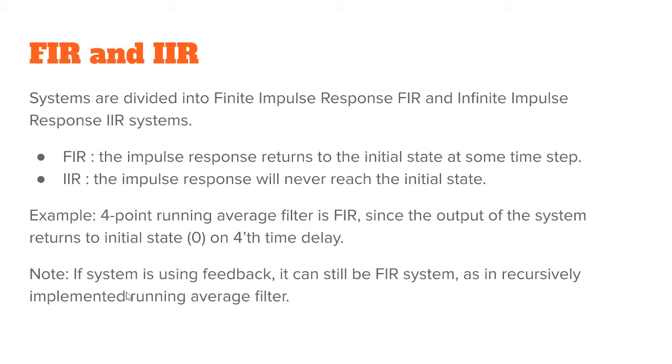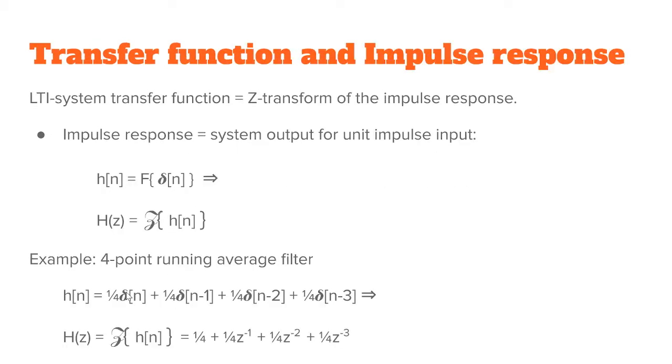That's the feedback when we take part of the output and put it back to the input, same way as you would do on the feedback on the analog system. Same thing. Yeah, but we have a feedback, but it is an FIR system since it's defined by what this impulse response actually looks like when it comes out.